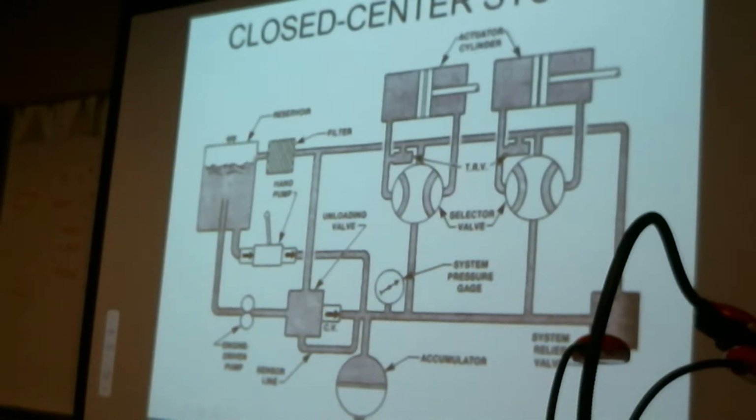And by having a thermal relief valve open, it exposed a path for both of the actuators to operate at the same time. So again, we cleaned the thermal relief valve out and replaced the fluid, and sure enough, that fixed the problem. But in any event, it's called a thermal relief valve.